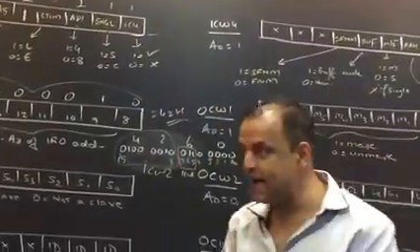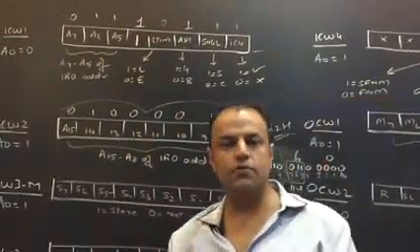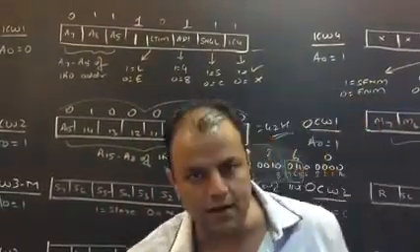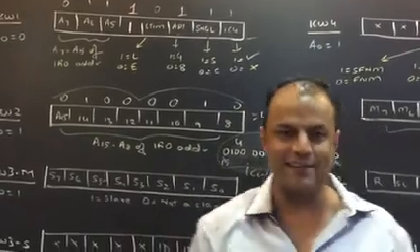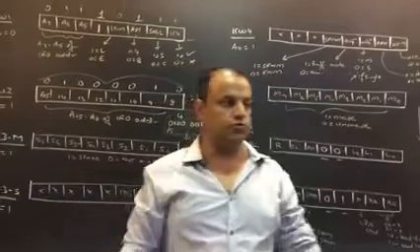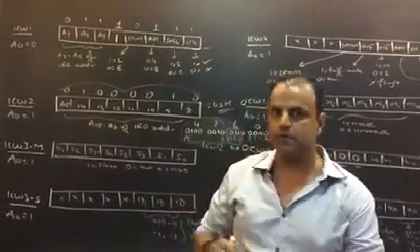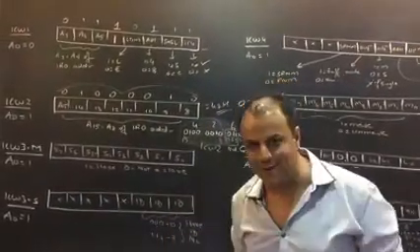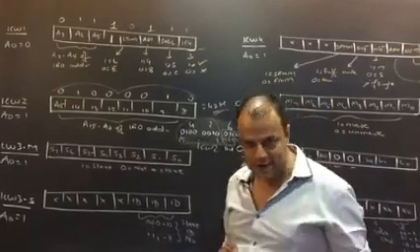Now, do you understand? ICW1 and ICW2 are the only 2 compulsory commands. 3 is given for cascaded, 4 is given if needed, OCWs are optional. So, suppose I am not giving anything else. My initialization by now should be over, correct?